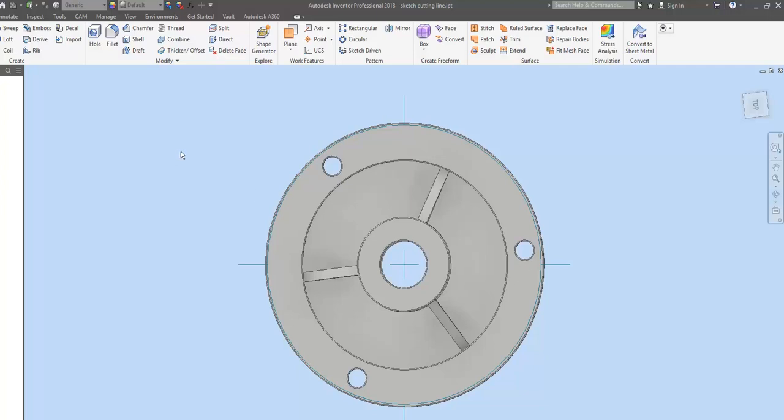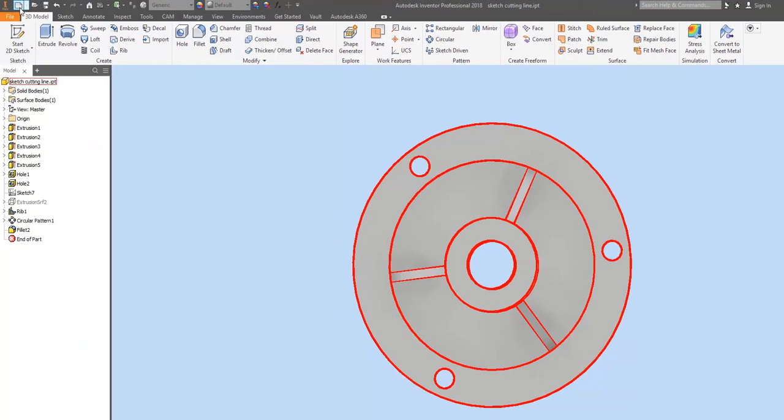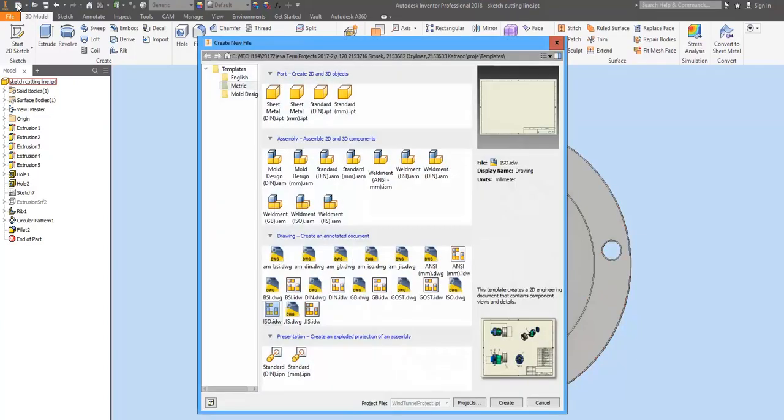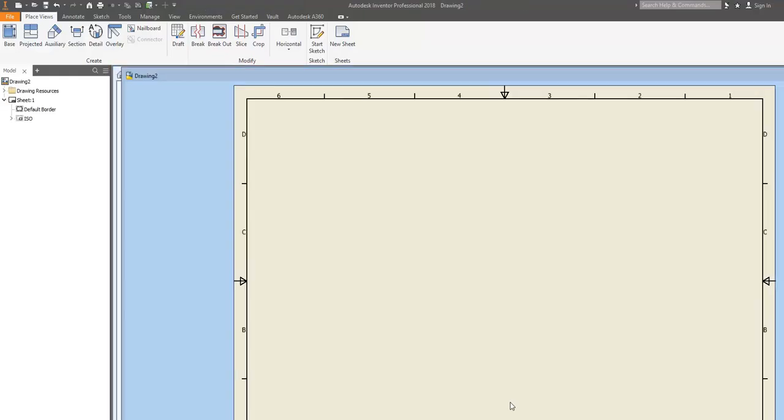Okay, start the view creation stage. You know how. Bring the cursor onto this icon. It is for new creation. And then in this dialog box, select the quadrant. Metric associates with first quadrant. And then obey the rules of ISO unless otherwise necessitated. Click on ISO template icon and then say create to have a paper simulation.